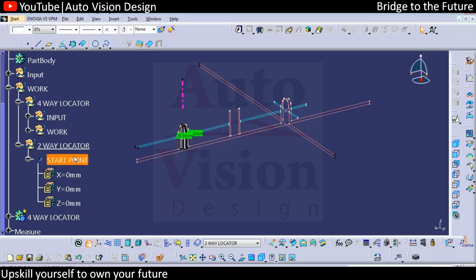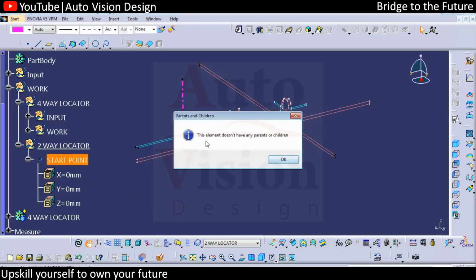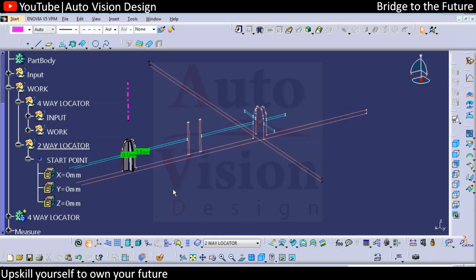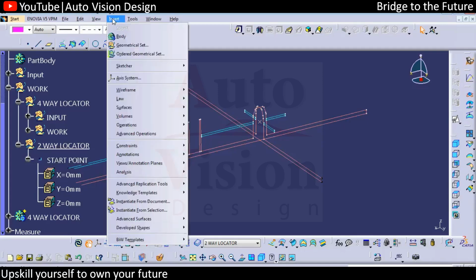Now if you check this point again, it doesn't have any parent or children right now. It will definitely have children once we add the power copy, but it has no parent. So this is a parametric point. Whatever we had earlier was nothing but a linked point. So we need to have this parametric. Then we need to recall the power copy.